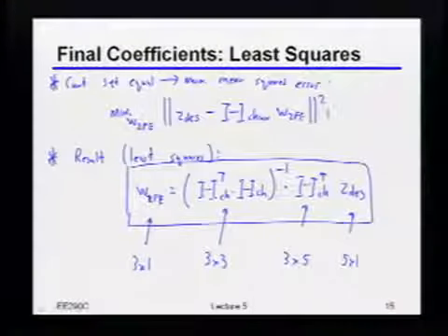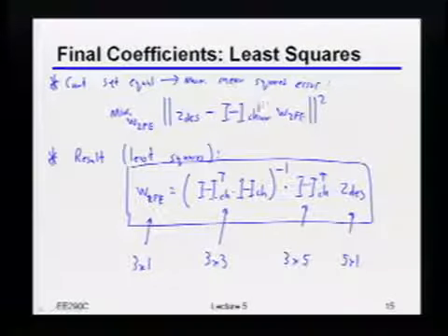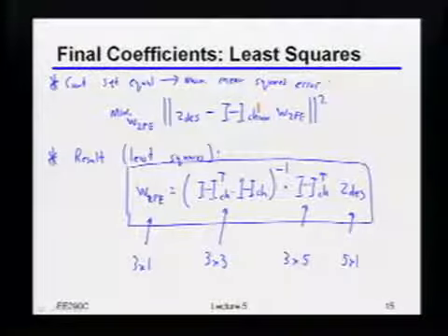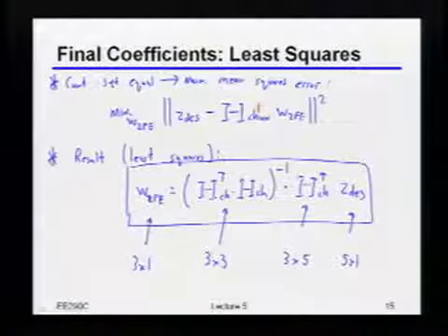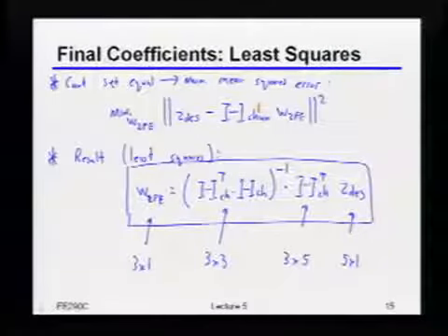The reason for that we'll actually talk about next lecture. It just has to do with the fact that when you write things this way, what you're intrinsically assuming is that the residual ISI looks kind of Gaussian, meaning its distribution looks like the distribution of the noise. But if the residual ISI does not look Gaussian or has some very different statistics, then this is not the Bayes optimal way of handling it. Okay? Like I said, we'll talk some more about that probably next lecture. But from 20,000 feet, that's the reason why there's a distinction there.